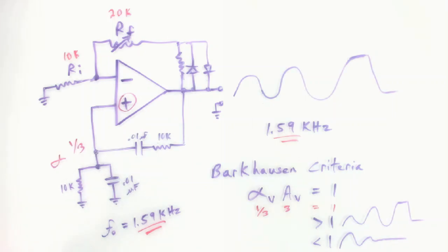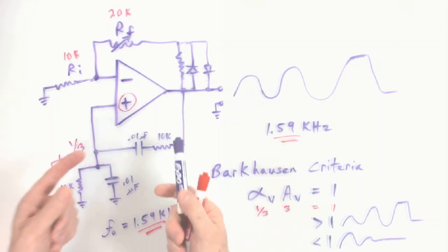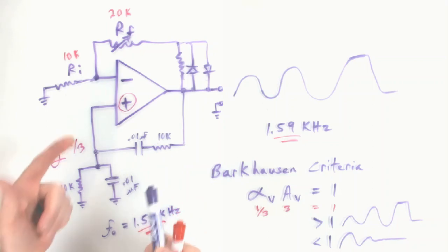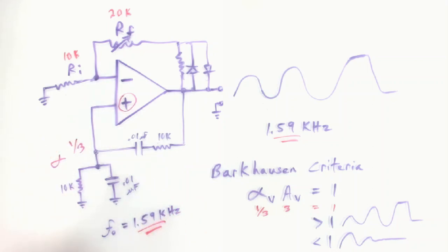And like we said, this is just one way you can make a feedback oscillator. There are many, and you can always look some up if you're interested in fooling around. I have a handout that shows a lot of different ones you can try. Maybe next year I can get that to you since we're via distance right now. All you have to do is meet the Barkhausen criteria. So whatever you're using for your feedback path for the positive feedback, you have to make sure you match the gain to it.